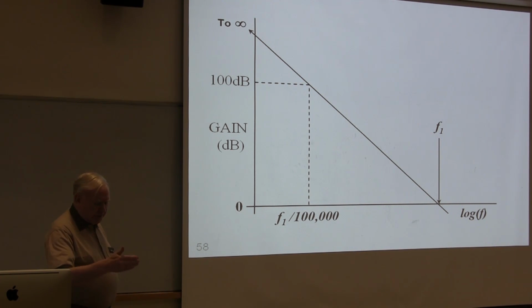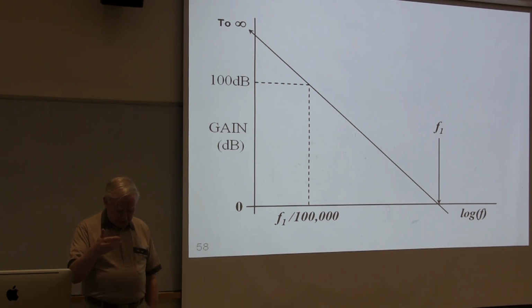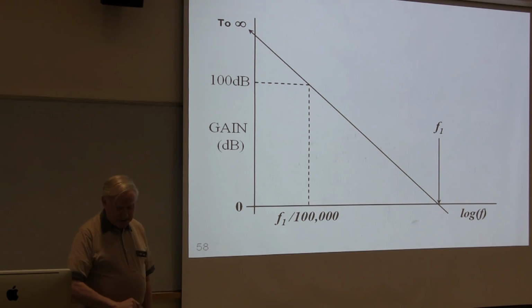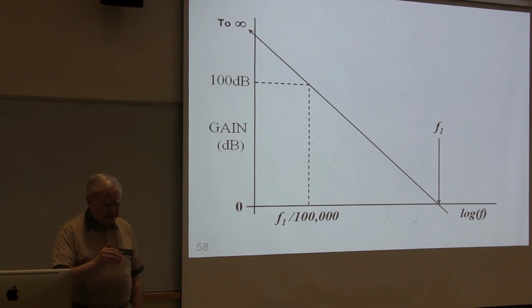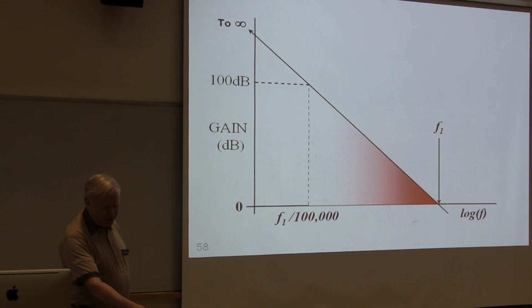And of course, at that point, because this is a simple single pole response in a dominant pole, we don't always use dominant pole compensation nowadays, that's true, but in a classic op-amp of the type I've shown a second or two, if the DC gain bottoms out at 100 dB, that's a corner, but the corner occurs at the unity gain frequency divided by, in this case, 100,000, which is 100 dB. So if this is, say, a megahertz, that's only 10 hertz. But that corner is not really a characteristic that matters. What really matters is this F1. That's the important point. And this region I've shown is the redder the region, the more useful the part is, until eventually, well, it really should have just a region in the middle, I suppose.